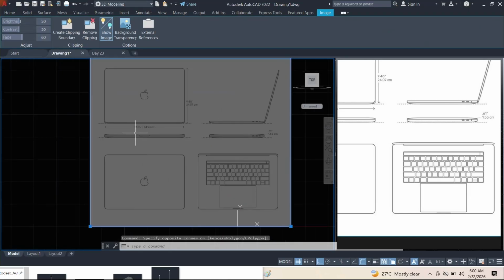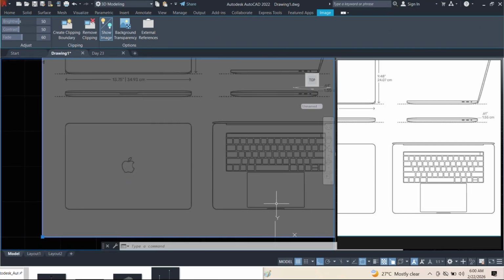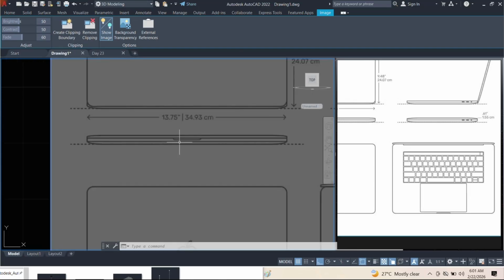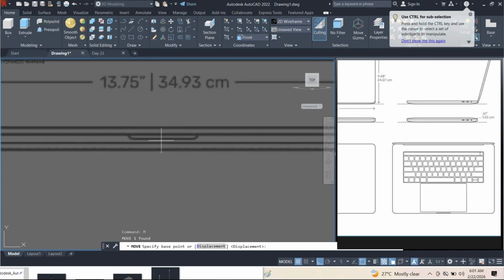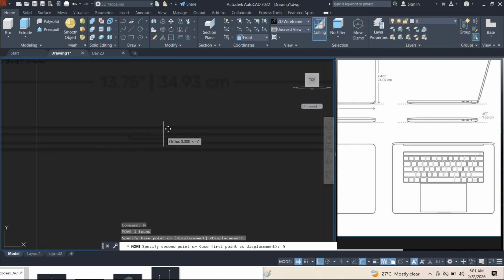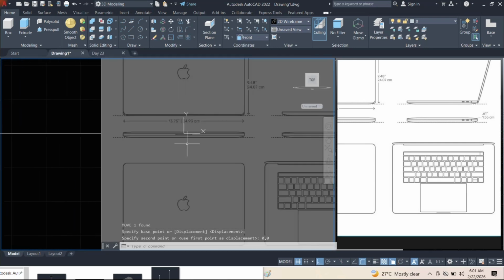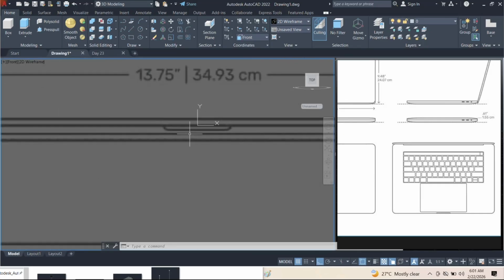This is my front view, right? So I'm going to move this one such that this place is in the origin, so that we can use that to scale up or down. Okay, so also have selected M for move. I'm going to pick somewhere here and then 0, 0, and then we'll shift it to the origin. So this is what we have, and then we can just extrude it downwards.